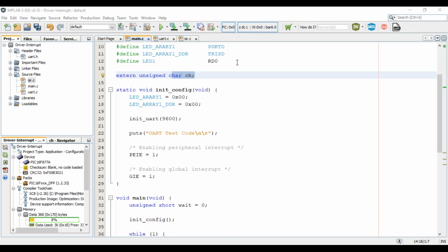Okay. And what is overrun error? We discussed it in the previous class. If you try transmitting a frame again and again, and the receiver is not able to accept the data continuously, it is going to give you an error. So the receiver will say that the data is being overloaded and it is not able to collect the data. So that's an overrun error.